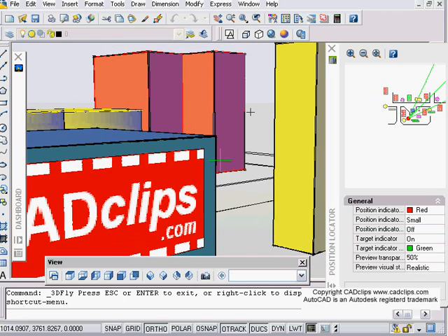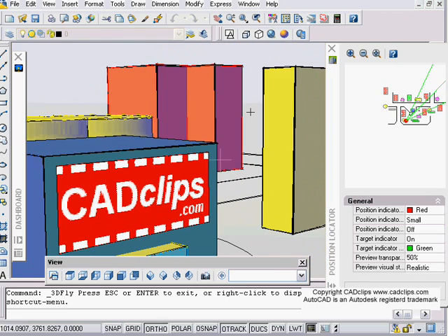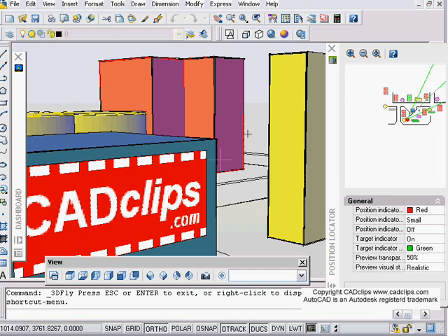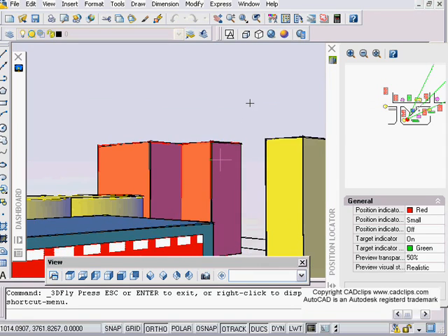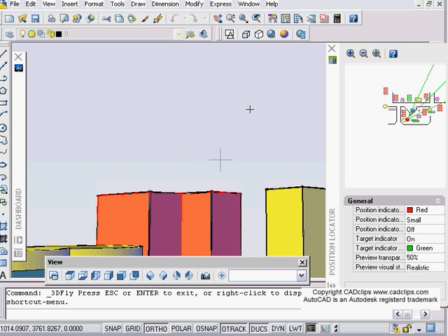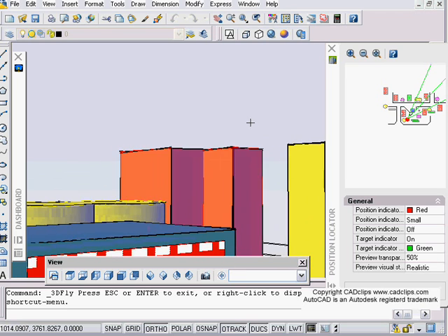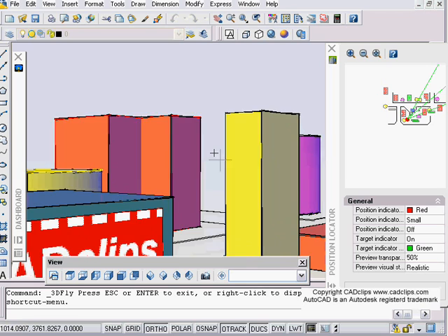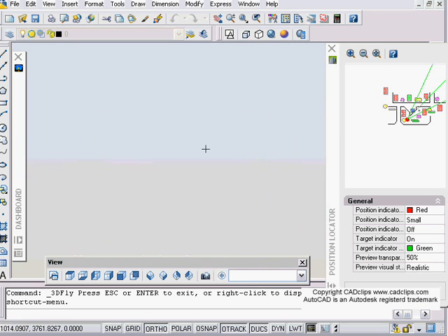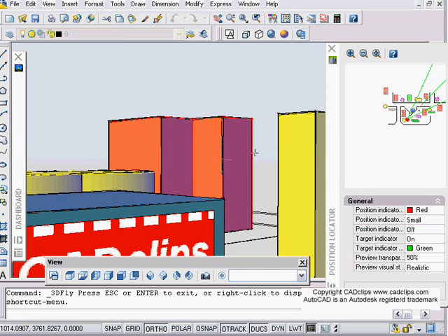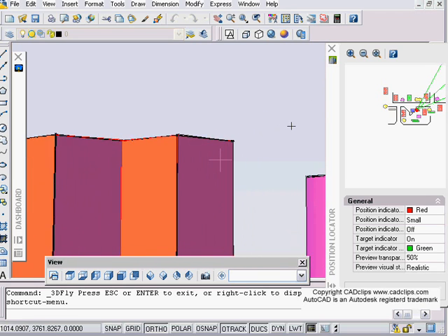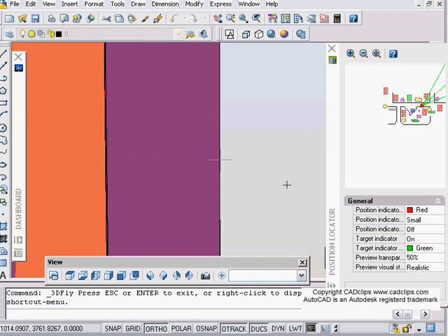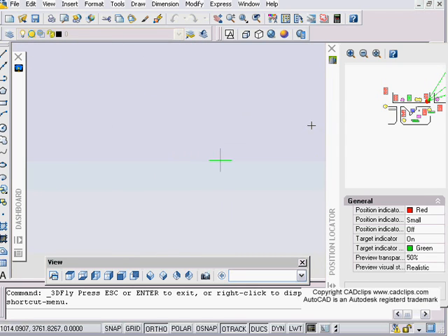At any point in here, you can just wheel in and wheel out with your mouse. Okay, just wheeling in and wheeling out. And then if you take your mouse and drag and let go with just your finger, regular mouse button, you can actually kind of pan around. Okay, and then sometimes you have to reposition yourself, and then again you can use your arrow key and you can continue that fly through and kind of skim up over top of these buildings, or you can go down